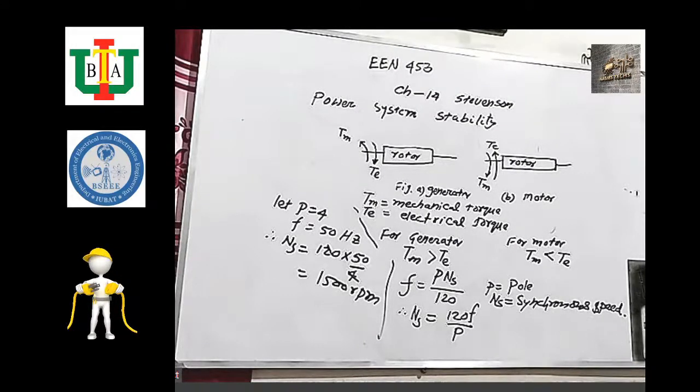The frequency is related to the inductive reactance of the circuit: XL equals 2πfL. So if the frequency increases, XL will increase. Then the current will also change, increase or decrease, like that. Power loss, power, everything depends on frequency. Understand?